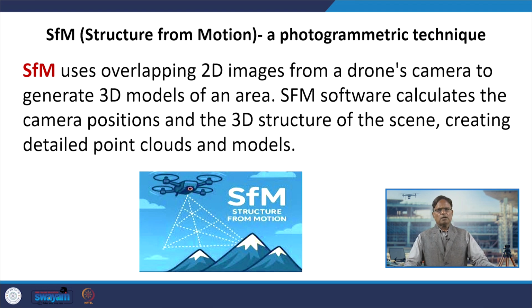Then there is a photogrammetric technique which is called structure from motion. So, what it does, it will use overlapping 2D images from the drone camera and will create a 3D model of the area. This particular software will compute camera orientation parameters and the 3D structure of the scene. So, you will have a detailed point cloud model from this particular software.